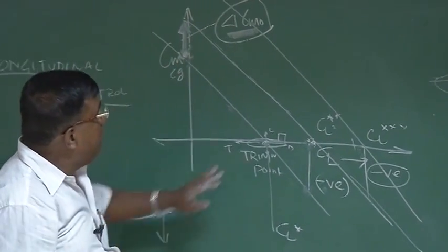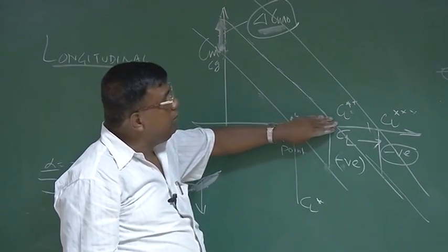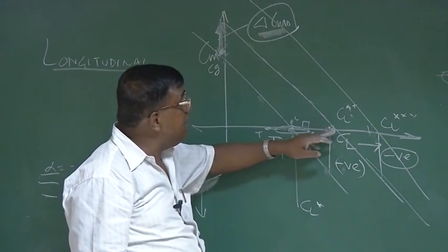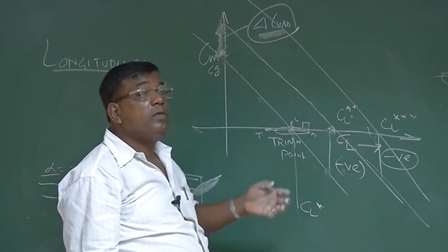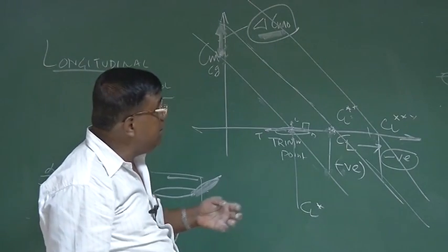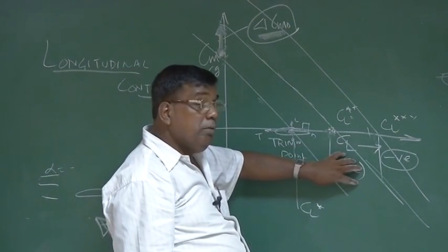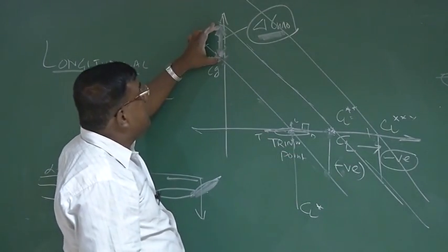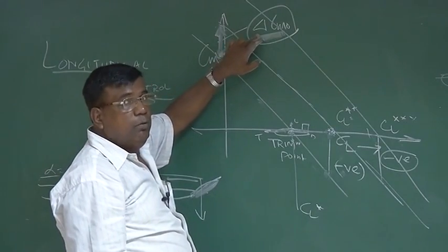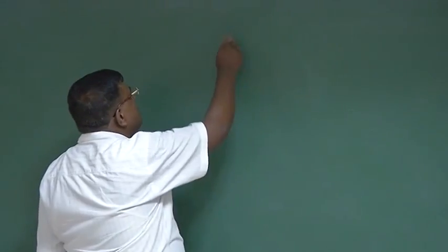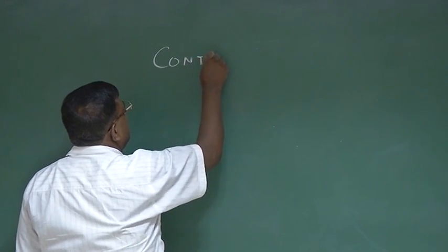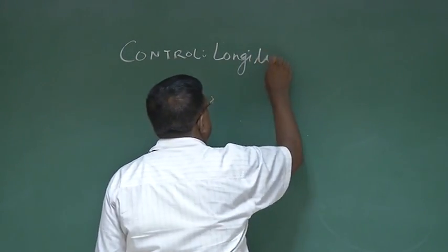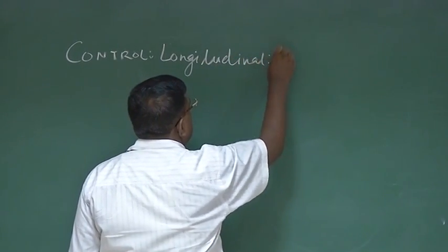Please understand, if I am trying to fly from one equilibrium to another equilibrium, because they are statically stable, they will generate negative opposing moment to discourage that change, and you have to give moment from outside. For a longitudinal control, it is elevator. See that whatever opposing moment is coming is taken care of. Equivalently saying, you increase the Cm0 by delta Cm0. Both are the same statement. Okay? So you are seeing one aspect of control, which is longitudinal, using elevator.